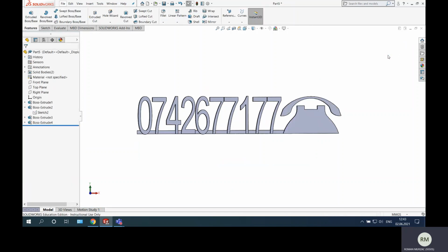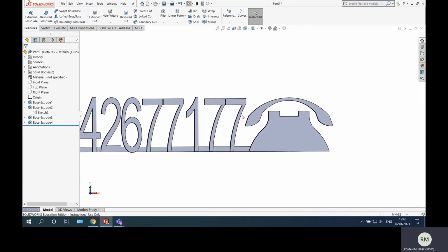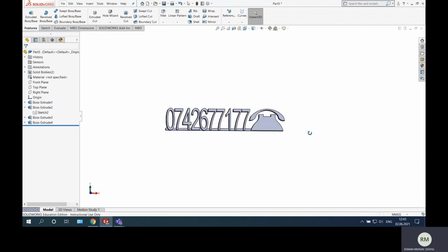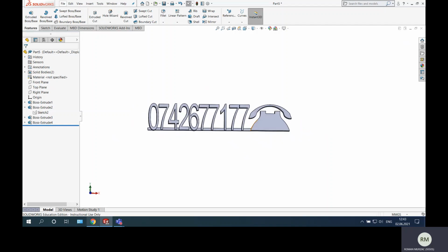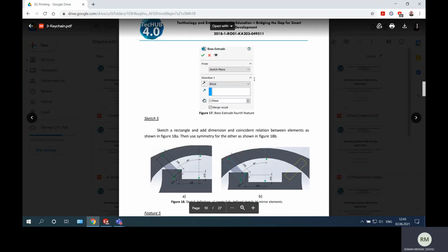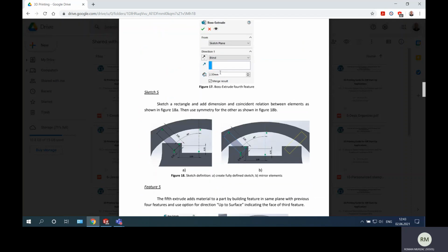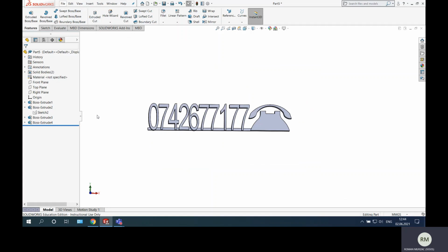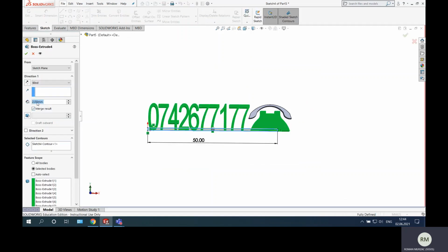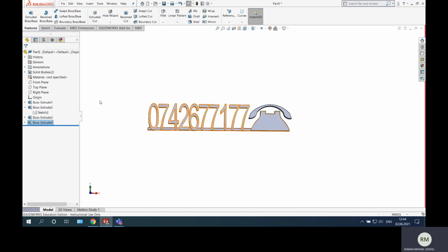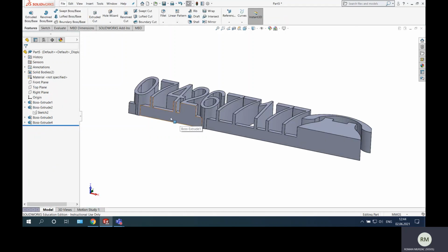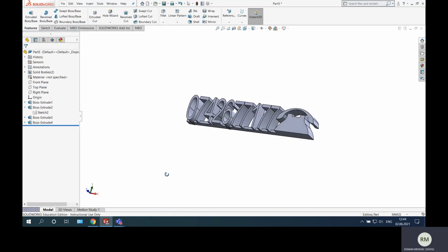Let's see what will turn now. Okay, I like it more now because it's more close. I create this bridge with 2.5. I extrude it with 2. So you can change it to 2.5, or I can change it from here, edit feature, and instead of 2 millimeters, say 2.5. So now our bridge has the height 2.5.